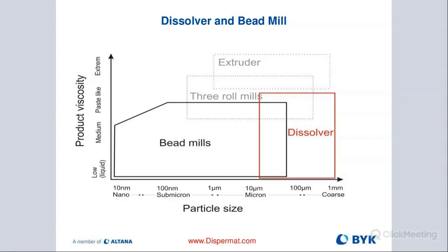At that point, you should start media milling. That's when you're more efficient. And as you can see, the dissolver stops at around 10 microns. And then we're not really putting in enough shear anymore to help us go down to the sub micron range or small micron range where we want to end up. We need to really media mill.